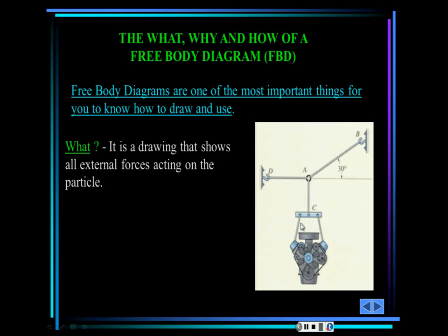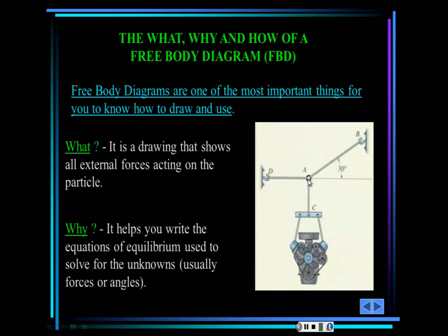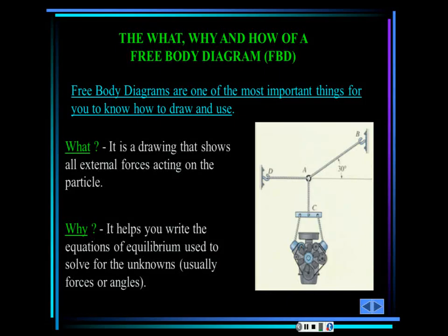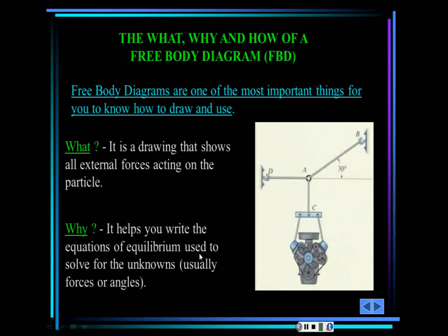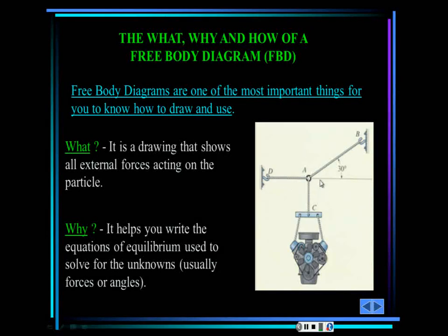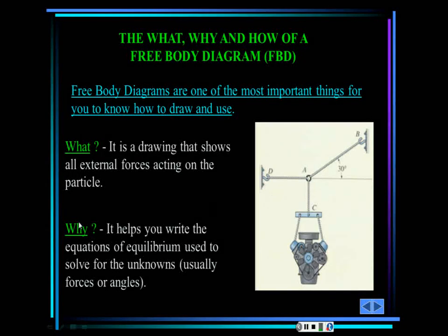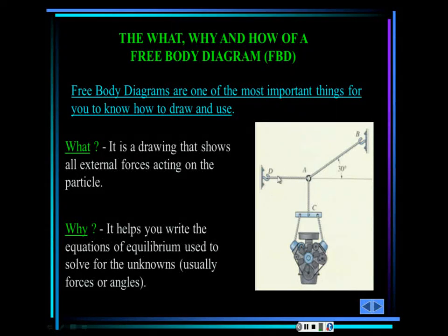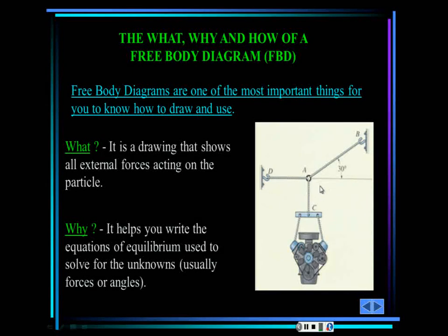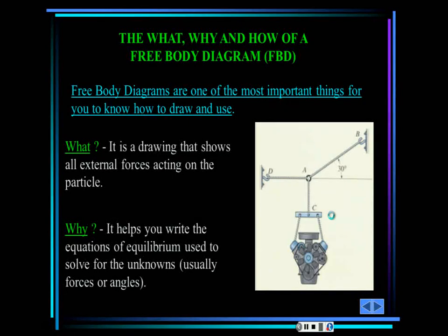Basically, that's a free body diagram: where the forces are located, how much is the value of the forces, or the nomenclature of the forces if you don't know it. Why do you do a free body diagram? Well, you do a free body diagram first because it shows you a simplification of the structure, and secondly because it helps you to create the equilibrium condition so you can set up the equation of equilibrium and solve that particular problem.